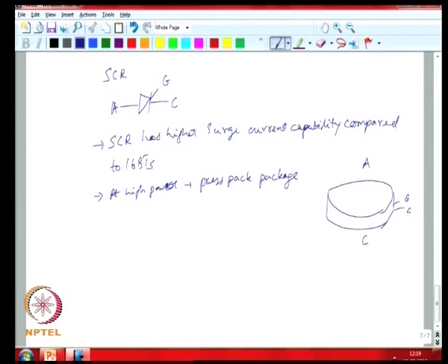So, to hold a PressPack device in place, you apply pressure on the top and the bottom, and that would mean that you have conduction of power loss from two directions compared to one direction for a traditional, say, IGBT module that is mounted on a heatsink. So, there can be advantages in terms of thermal resistances.